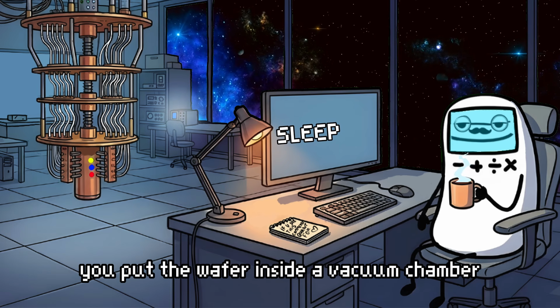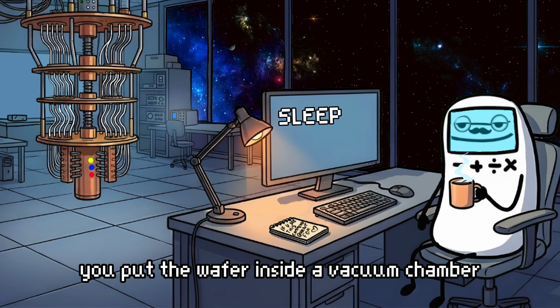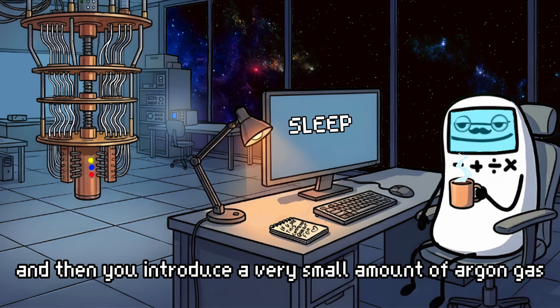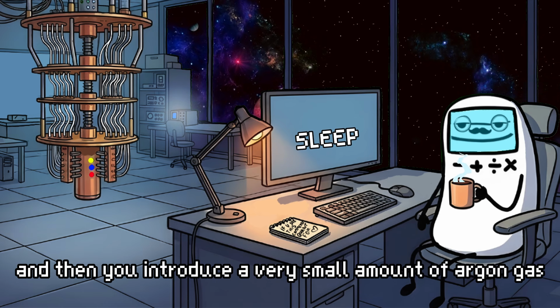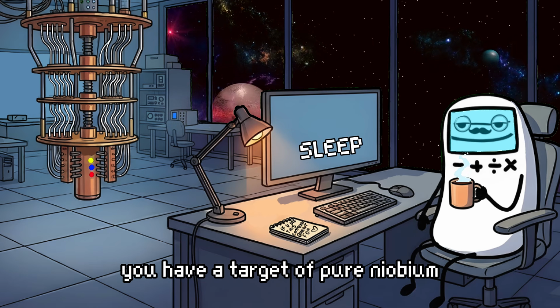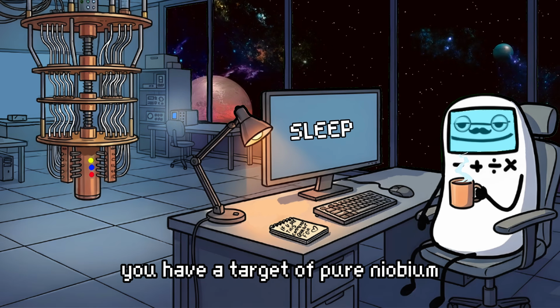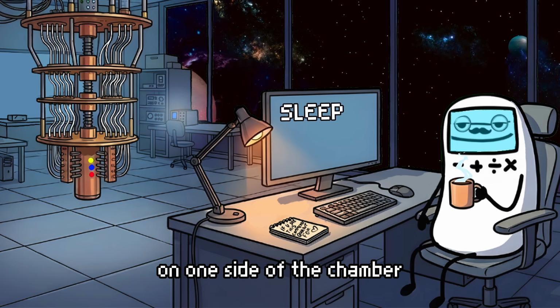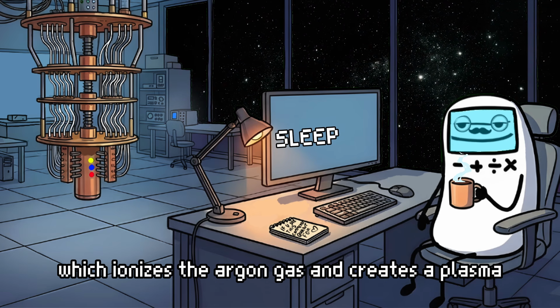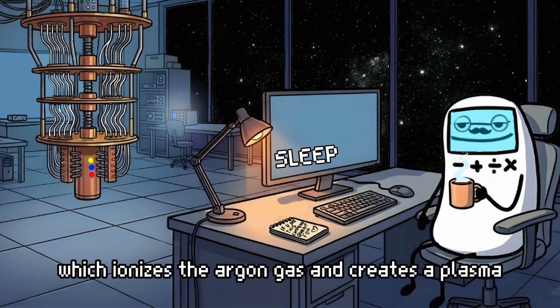You put the wafer inside the vacuum chamber, pump the chamber down to a really good vacuum, and then you introduce a very small amount of argon gas. You have a target of pure niobium on one side of the chamber. You apply a high voltage, which ionizes the argon gas and creates a plasma.